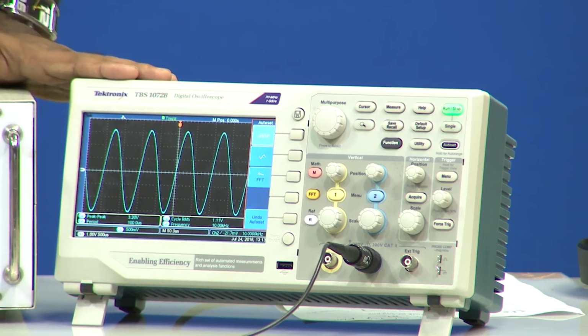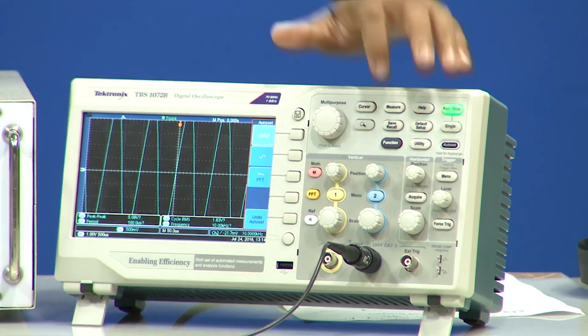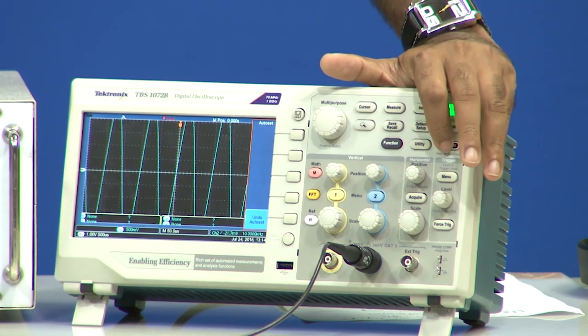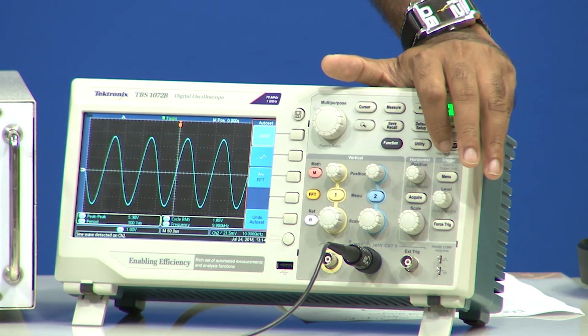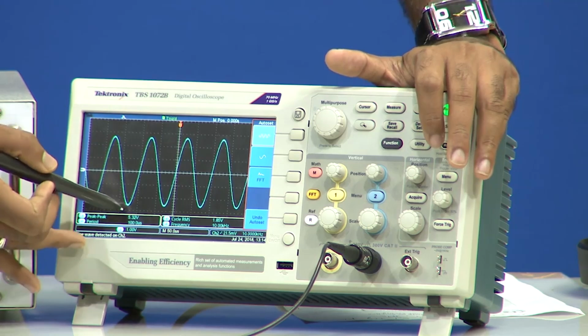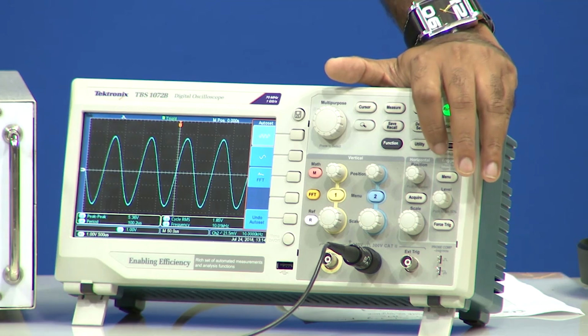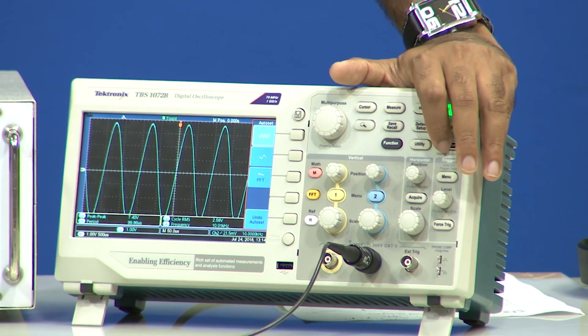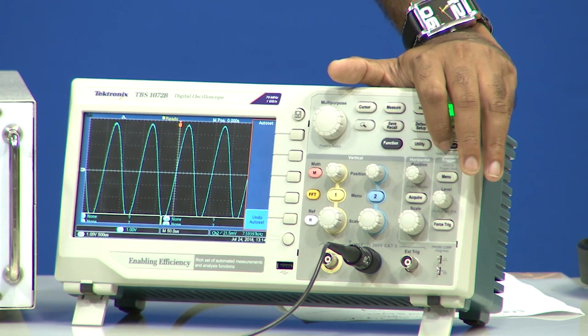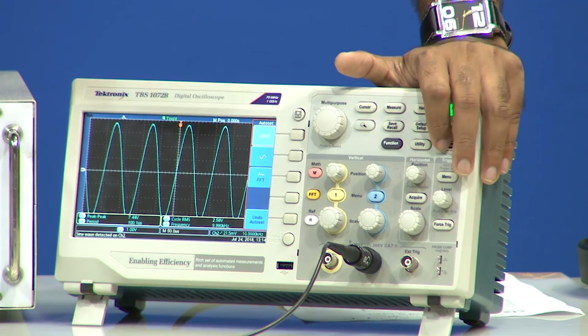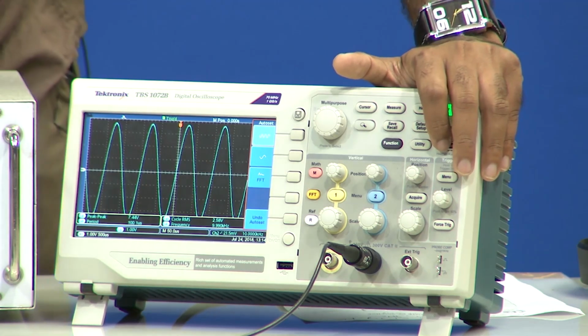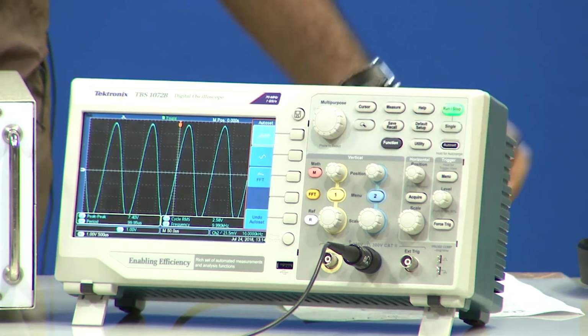Now, let us change the input. I am going to change the input in steps of 1 volt. So, from 1.5 volt, I am changing it to 2.5 volt. Okay. Let us do an auto scale so that we can see the whole signal. So, we can see the whole signal. Now the output voltage is 5.32 volt, which is again matching, correct. So, 2.5 volt. Now, again I am increasing it to 3.5 volt. For 3.5 volt, what is the output? We are getting 7.4 volt, again matching with the 2.2 gain formula.